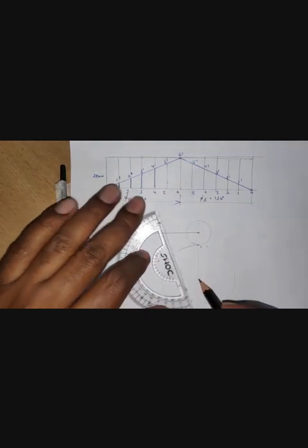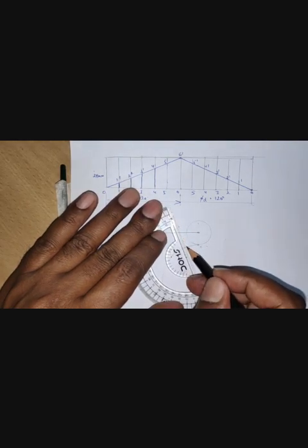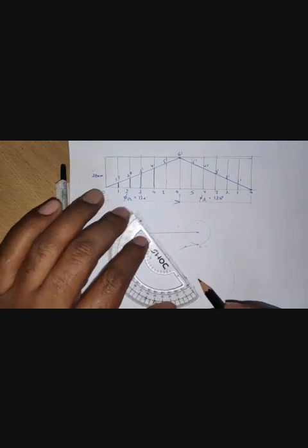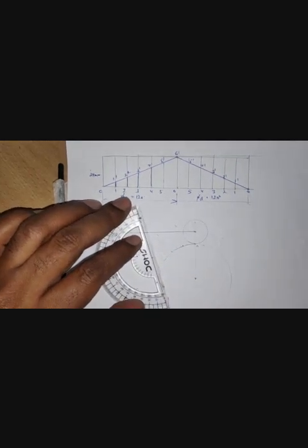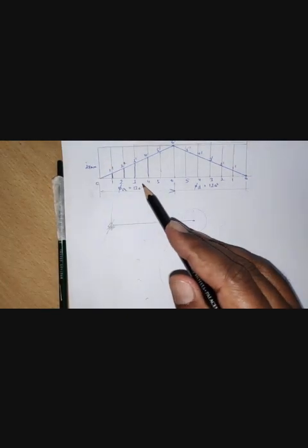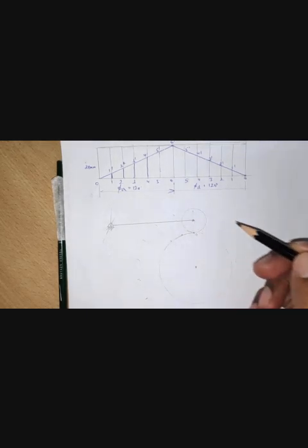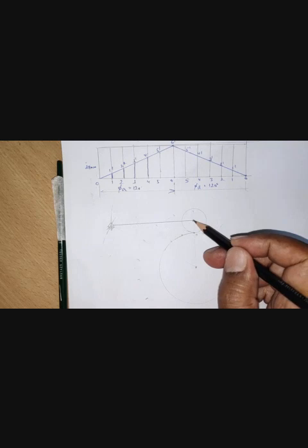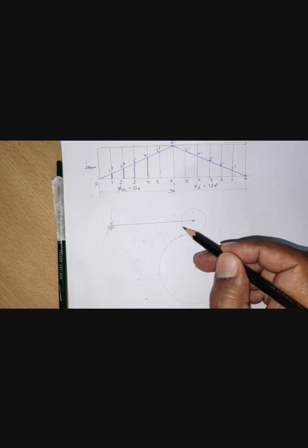Once I have done this, then on the base circle I can locate these points here. So you don't have to draw the radial lines; you just have to keep the scale like this to locate these points. Of course, before locating this, I have made a small mistake. The locations of 0, 1 to 5 are not on this base circle, because for a roller follower, the trace point is not this point, the trace point is this point, because the cam can come in contact with any of the roller points here on the periphery.